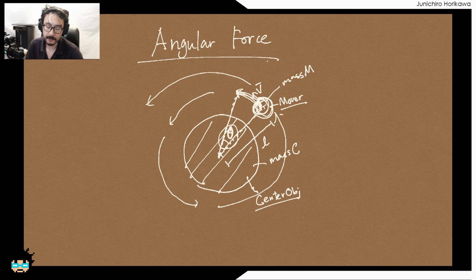So we also need to limit the maximum speed at some point, if we don't want the really top speed. Now in Houdini, we're going to create an angle using the float, and I'm going to use the matrix to create the rotational matrix, and then apply it to the point positions to actually rotate the point as a vector value.